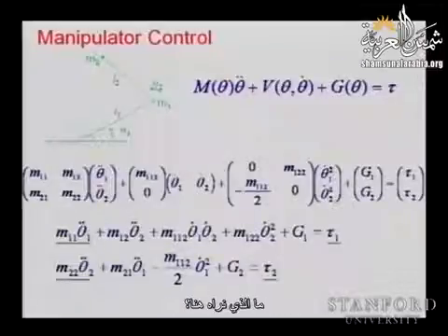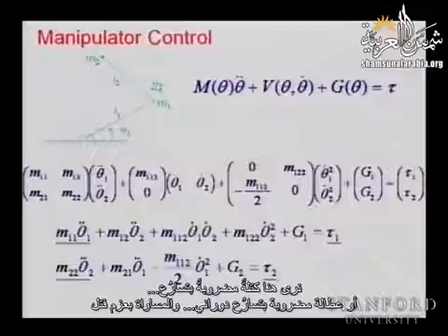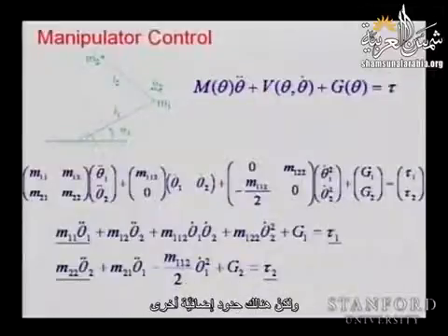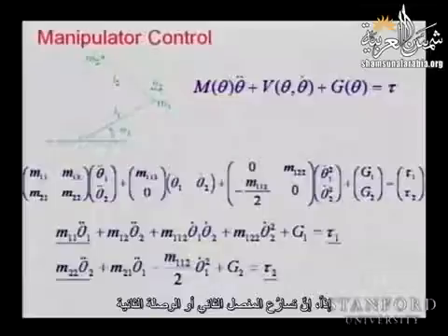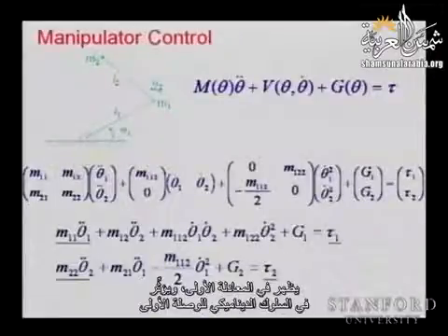So what do we see? We see here mass times acceleration, or inertia times rotational acceleration, equals torque, but there are all these additional terms that are appearing. Essentially, the acceleration of joint 2, or link 2, is appearing in the first equation and is affecting the dynamic behavior of the first link.